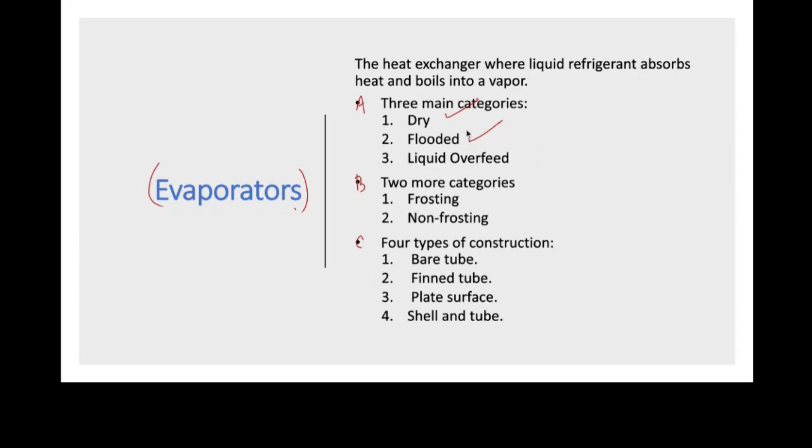And so a flooded evaporator is far more effective. You get a greater heat transfer with the flooded per unit time, per unit size, than for the dry type of evaporator. Now, number 3 is the liquid overfeed evaporator, which is the most important in industry today.